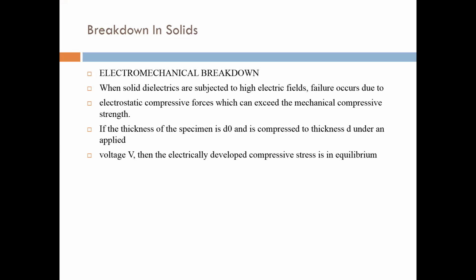Every solid dielectric has a certain mechanical compressive strength. When these electrostatic compressive forces, due to the high electrical field, exceed the mechanical compressive strength, then electromechanical breakdown occurs in the solid dielectric.